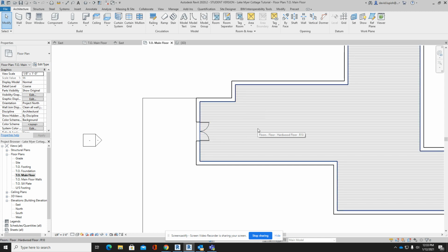In the case of stone or any masonry type of construction, we will install the inside face of the sill plate on the inside of the foundation wall, because we have to allow a spot for the stone or brick or masonry unit to rest directly on top of the foundation wall. And then the leftover dimension becomes our airspace.